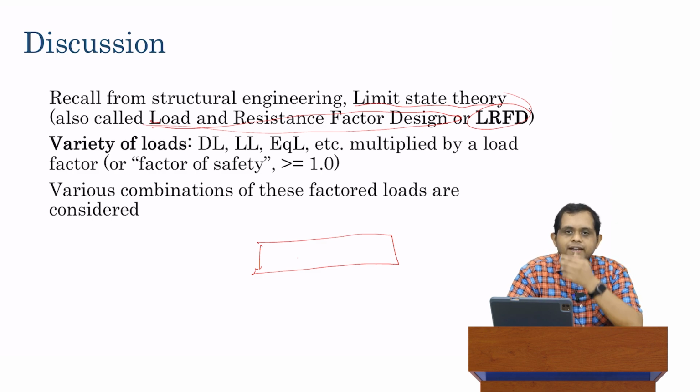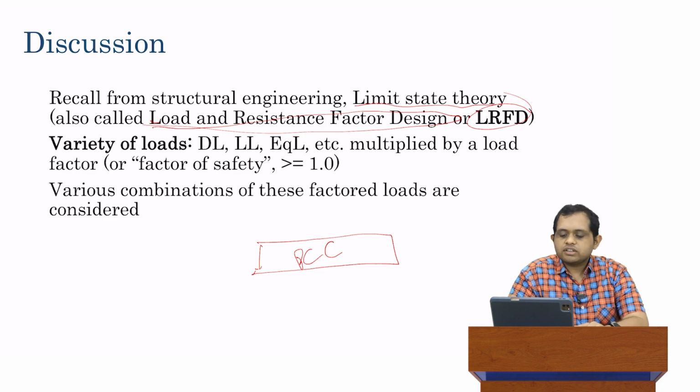So suppose we want to design a beam. The first thing we have to choose, of course, is what is the material of the beam. So, of course, we will choose it's Portland cement concrete. So, that's easy to take care of. Now, what we first need from the design method is what loads should we apply. The LRFD method gives us a series of different types of loads to be considered.